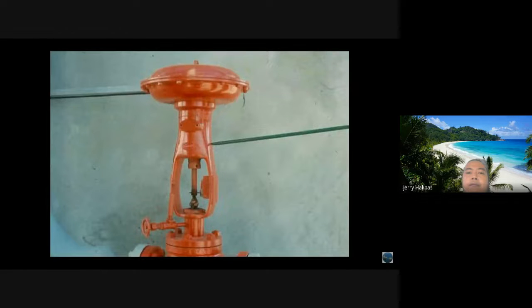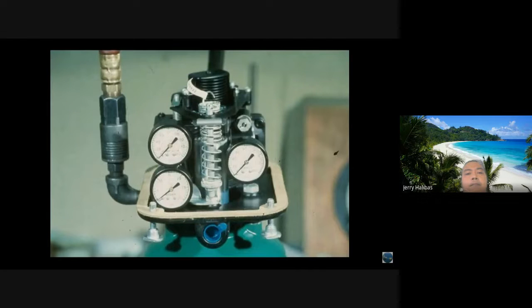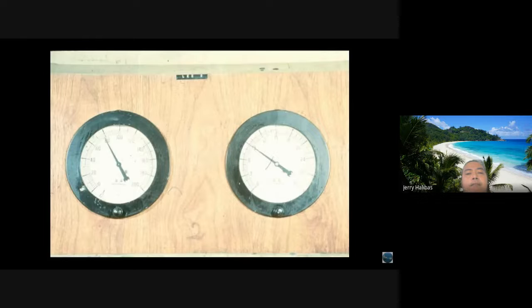The proper signal is present at the actuator, but it still will not operate properly. A spring-opposed diaphragm-type actuator will rarely have anything out of order other than the diaphragm. But the piston-operated type actuator, since it is more complex, may have other problems. Assume this piston operator is receiving the proper input but won't move. First, check the obvious. Make sure you have an air supply between 35 and 100 pounds and a valid input signal.